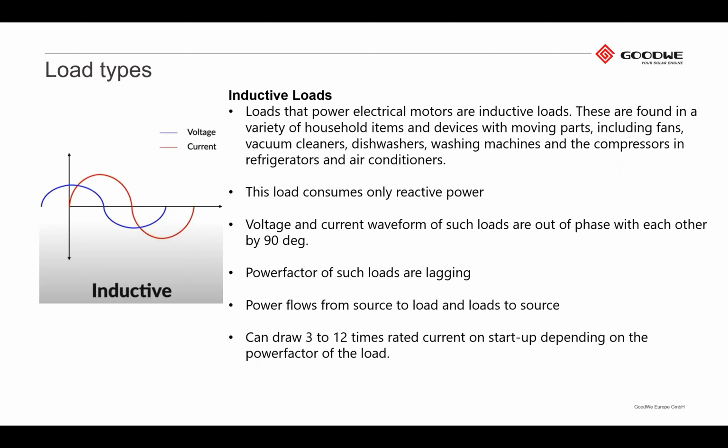This load consumes only reactive power, so the voltage and current waveforms are out of phase by 90 degrees. That's why it consumes reactive power, because the voltage is leading the current. So it has to ramp up the voltage first, and then the current ramps up.